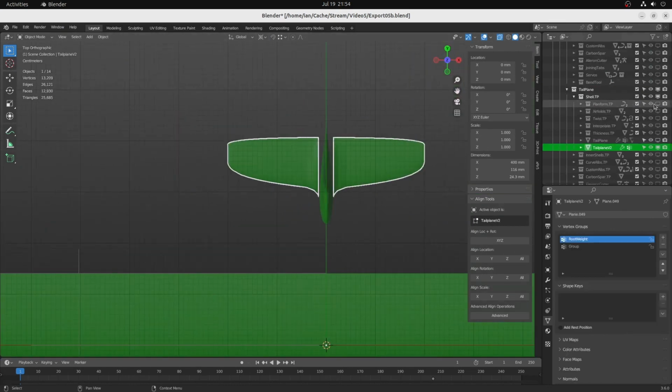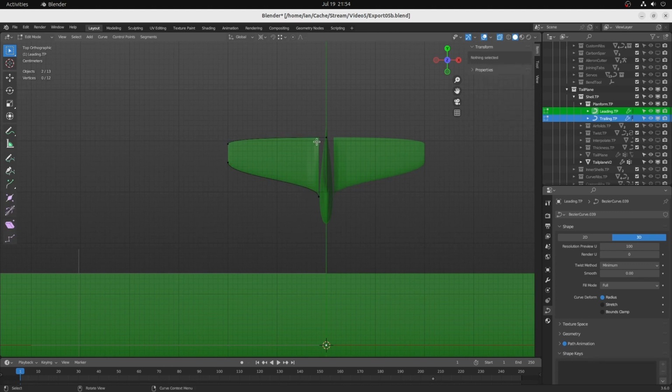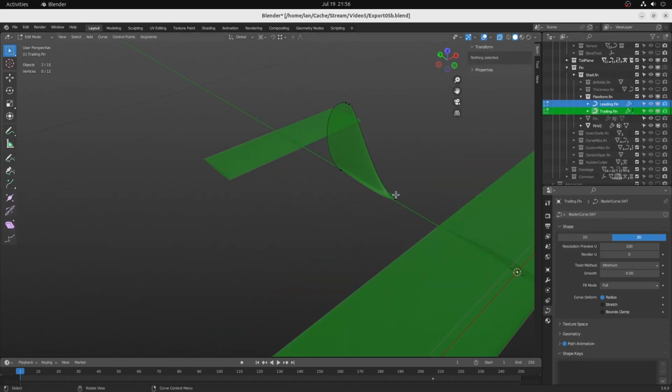So what's a good spacing between the main wing and the tailplane? Not a lot of internet advice on this, but somebody says 2 wing chords, so I'll try that. The tail aspect ratio should be quite a lot smaller than for the wing, so perhaps 4 or 5. A tail volume of 0.5 and a fin volume of 0.02 is suggested, so that gives me the tail area.